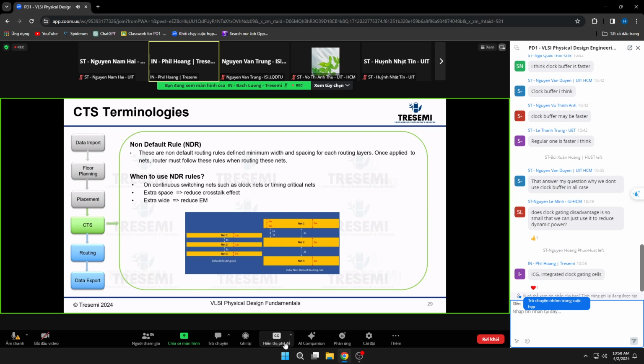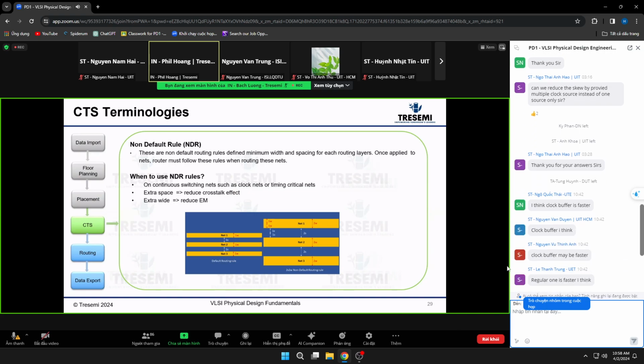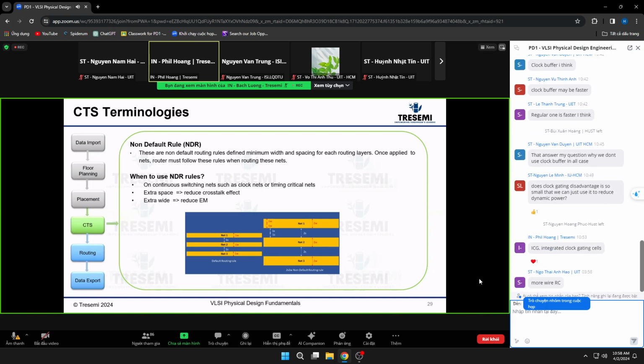So it increases the capacitance, right? Yep. More C. RC will be improved, but the power, more C, right? So you're switching more capacitance. Therefore, you increase the dynamic power, which can be very significant because clock power is about 1/3 of the whole power. You remember the C load is part of the dynamic power.